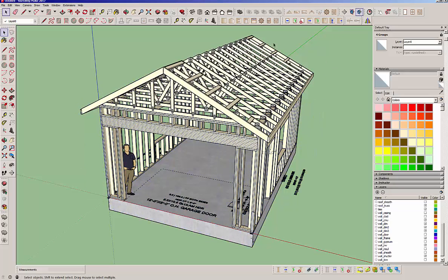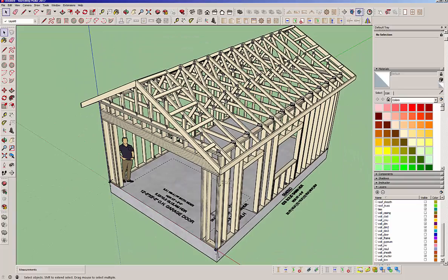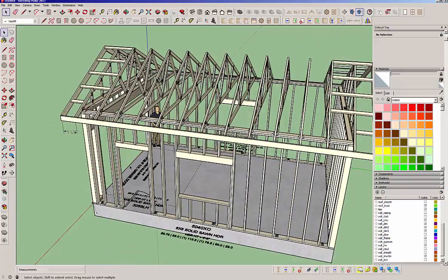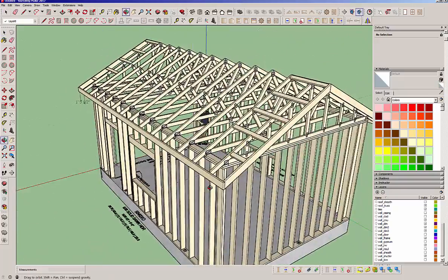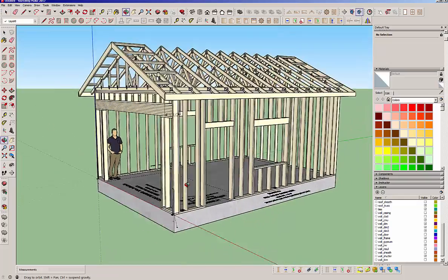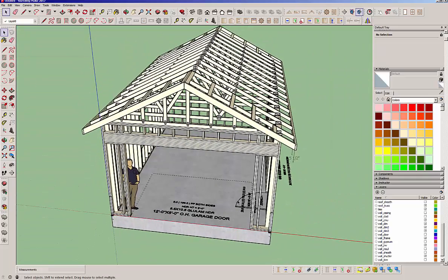And then ultimately, you've got the engineering piece, and I want to have it so that a guy can come along here, click this engineering button, enter in a few site parameters for the job site, and then we do the vertical calcs, we do the lateral calcs. We can check what we need for shear walls and get those in there. We can check the headers for vertical loads, snow loads, etc. Also check the foundations.